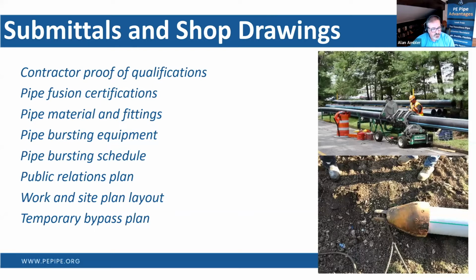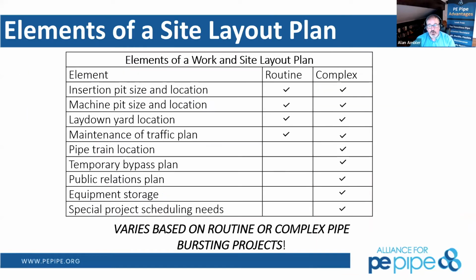So here, one of the things that we're paying attention to also is bypass plans. As that pipe gets bigger, so does the challenge of a temporary bypass as we look forward. With a lot of these site layout plans, when you have an owner very familiar with pipe bursting, sometimes some of the more complex aspects are not necessary within the actual plan. When we get into very complicated projects that require a lot of attention, then you would develop more of that site plan.